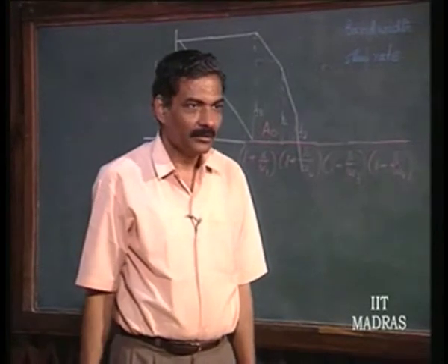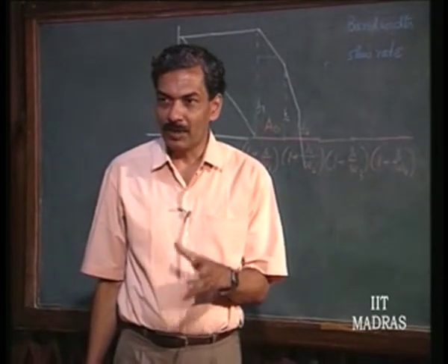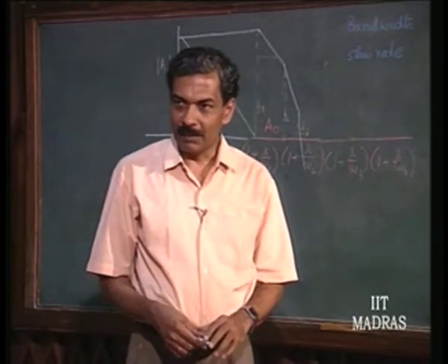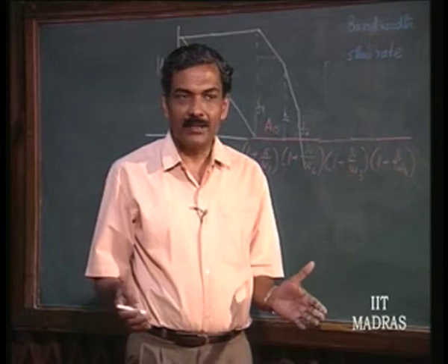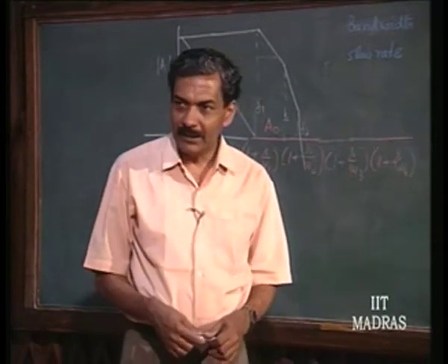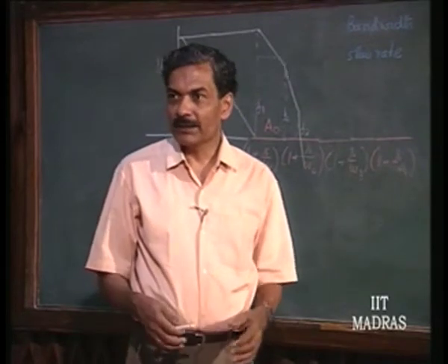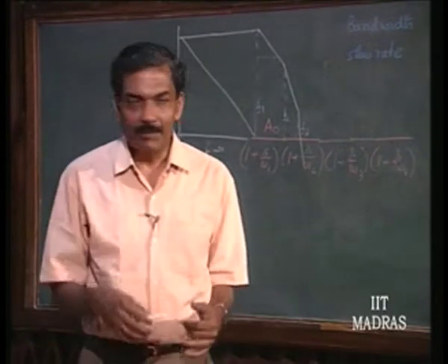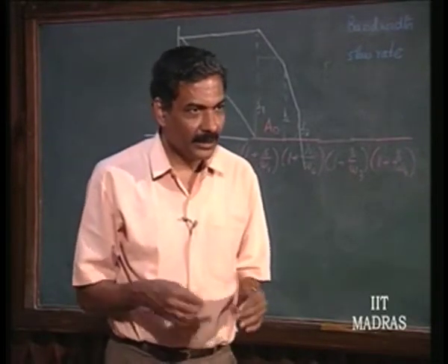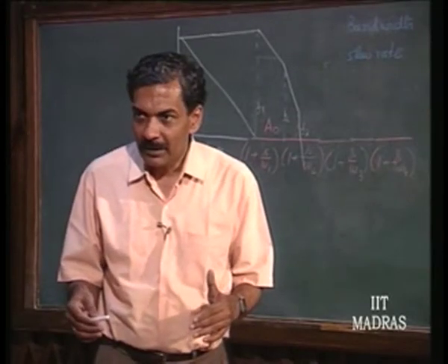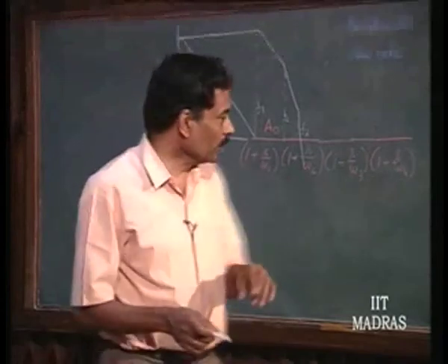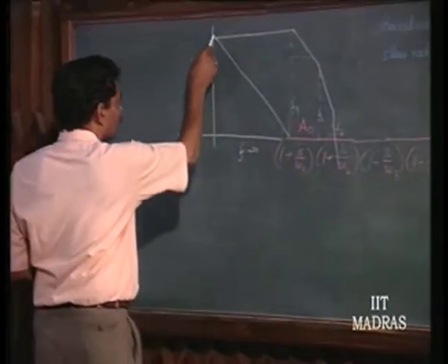Okay. That is what is called dominant pole compensation, which is universally adopted for most of the internally compensated op amps. So, that anybody using it will never get trouble. There is enough margin of safety, so that it works even if there is additional phase shift given by the beta determining network itself, still it is not going to be unstable. So, for this eventuality, you cut down this gain.